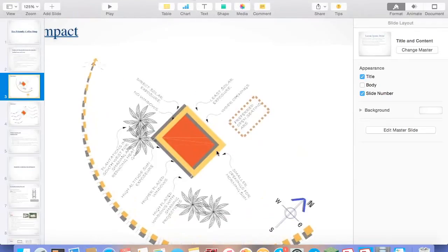See, we should have smaller openings here on the east side for the morning sun. We should have maximum openings in the north because here we hardly have any sun rays and the least solar exposure is there. Here there is a direct solar exposure, which is the west direction, and it should not have any windows.